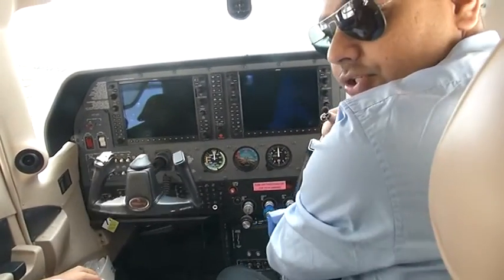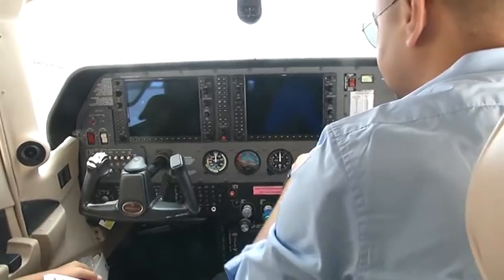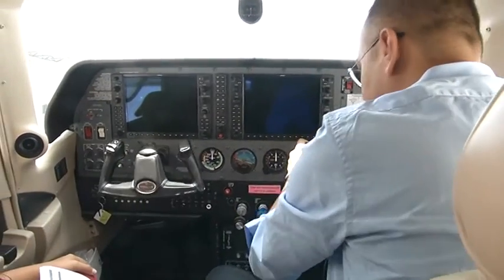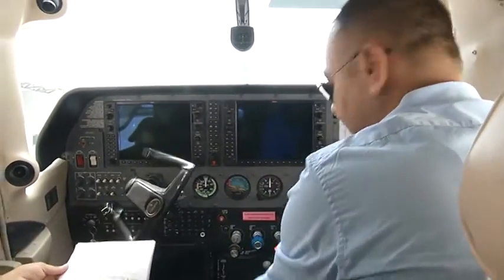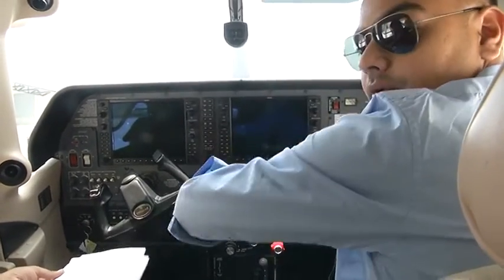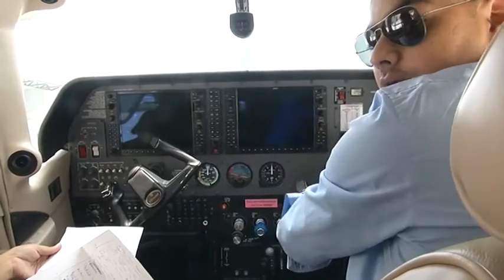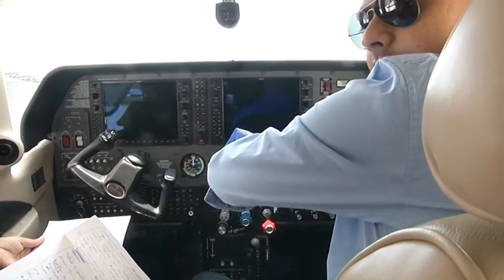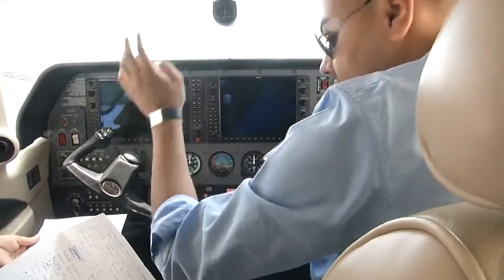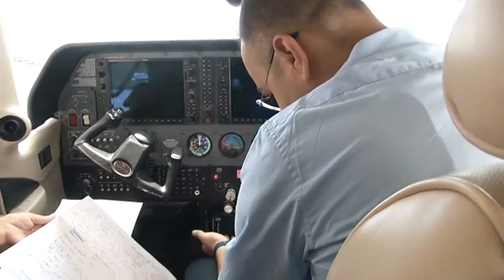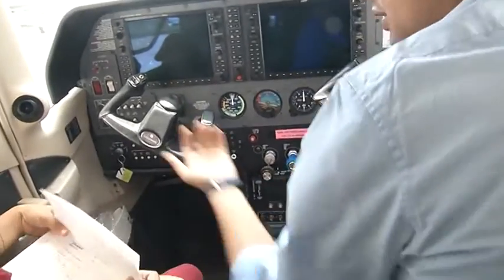Okay, pitch: if the control column is moved backward with pressure, the aircraft goes up; forward, the aircraft goes down. That is ailerons, left or right. You can turn left, left wing below the horizon, right wing up. If you press right, then right wing below the horizon, left wing up. Okay, and then the two rudders jointly. Okay, then we can start.